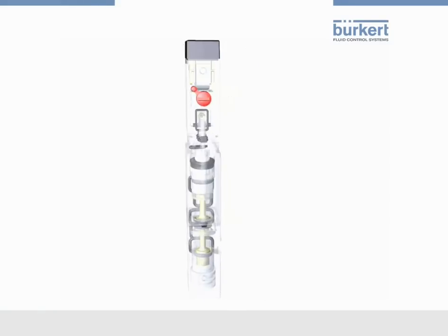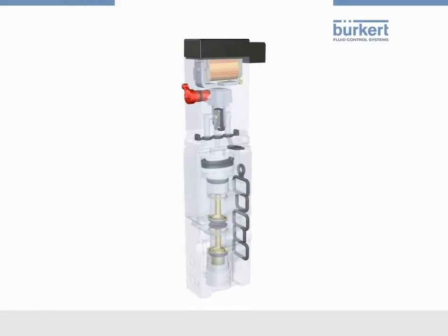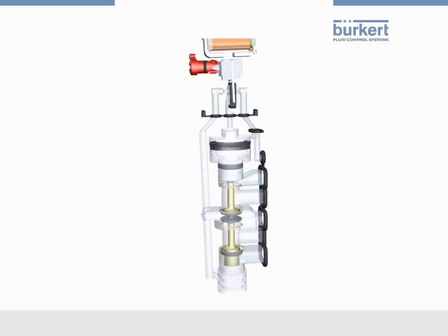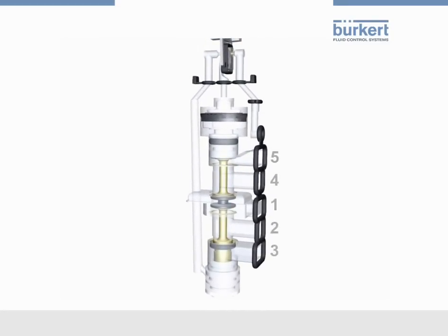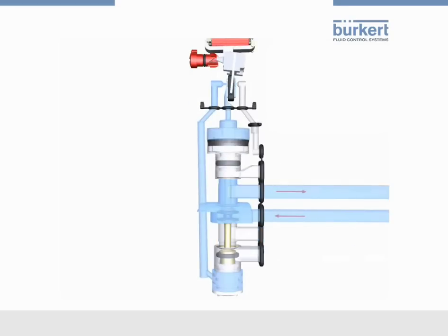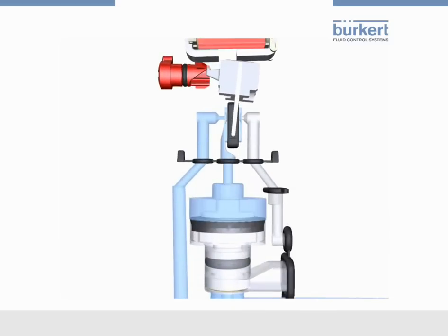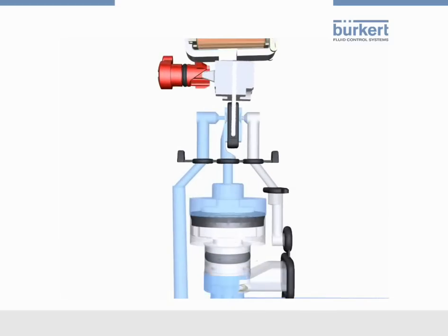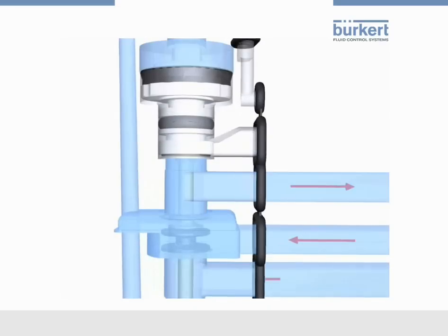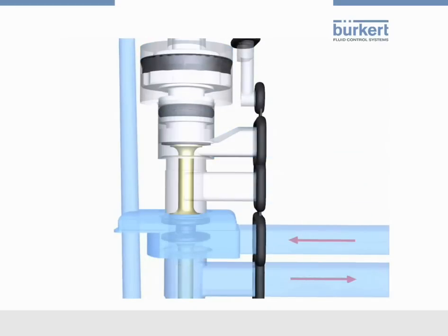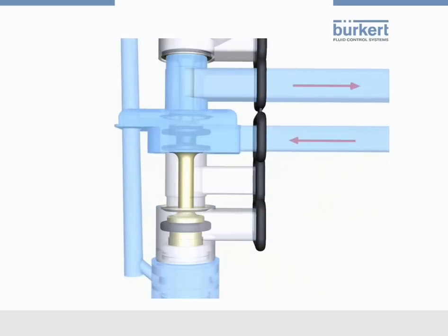By looking at the function of the Type 6525 as a 5-2-way valve, we'll bring the part with single pilot valves to a close. This valve has 5 connection ports, like the double 3-2-way valve. The valve doesn't fulfill a double 3-2-way function, but serves as actuation for a double-acting actuator. Here you see the switching of a 5-2-way valve. The function principle is the same as for type 6524.